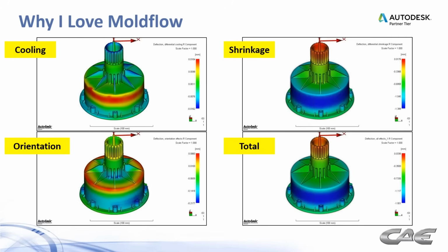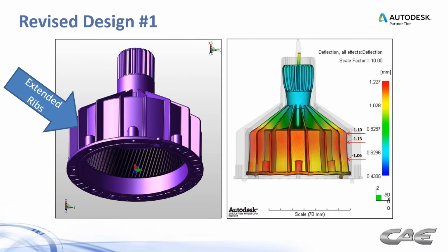And one of the things I like to do on any project I work on is not rely on processing to fix my parts. If you have to rely on processing, oftentimes that's telling you something. You've got a very tight molding window, and it's harder to hit that bullseye. So we want to try to hardwire things into either the part design or the mold design, preferably the part design. Hardwire solutions into it, that is. So that's where we looked.